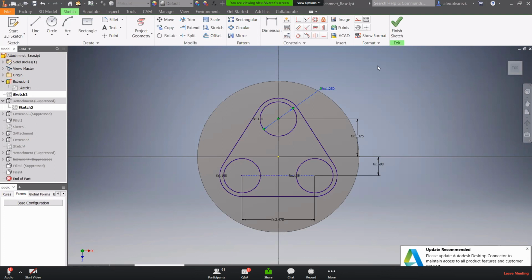It's like, well, it makes it easier if, when you're making these sketches in the first place, you denote those dimensions as whatever the parameter is in text, equals, and then whatever number or equation you want to use. Even if you're not going to be doing design automation, that's just good practice. Maybe down the line you decide to do some sort of automation with that part. It's already going to be set up for you and ready to go, right? It takes a little bit longer to do the parameters, but down the line you're just going to be helping yourselves out, at the very end.